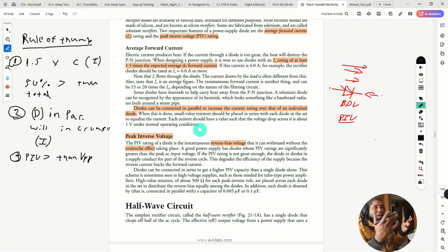And that kind of makes sense, right? We don't have to think that much about that. It's like you want your reverse bias limit to be higher than what your peak voltage would be. So if we were using 120 volts, we want that breakdown voltage to be somewhere like 200 volts. Okay, so there's no chance of that, because you know that 120 volts can spike and all kinds of things, right? Especially when you just turn things on, or if you have a large capacitance reservoir, then your 120 volts could go up to 160 and stuff like this. So you get very close. So you want to make sure that breakdown voltage is much higher than the voltage you're actually operating at.